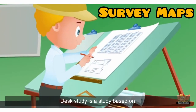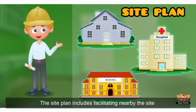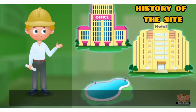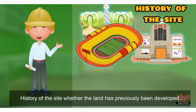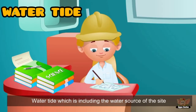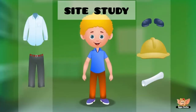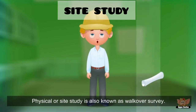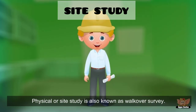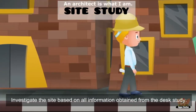Desk study is a study based on survey maps, including transport links with the location. The site plan includes facilities nearby the site, the history of the site, whether the land has previously been developed, or used as a site for rubbish disposal, and water type, including the water source of the site, such as river or sea. Physical or site study is also known as a walkover survey. Investigate the site based on all information obtained from the desk study.